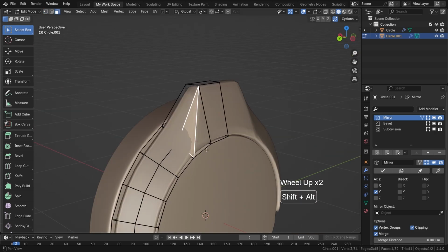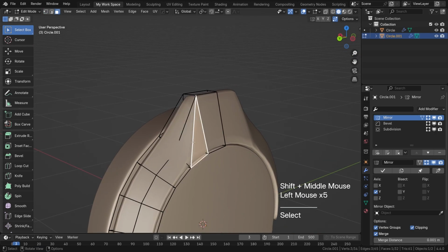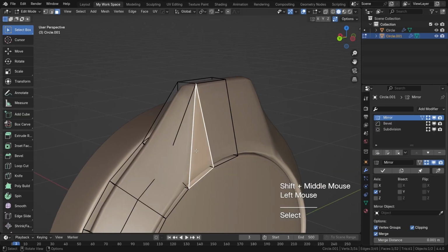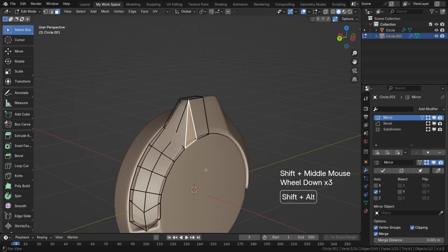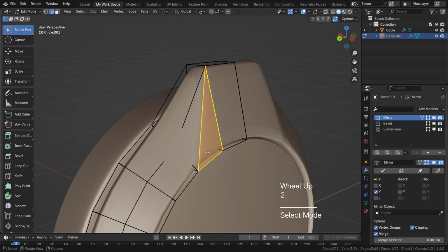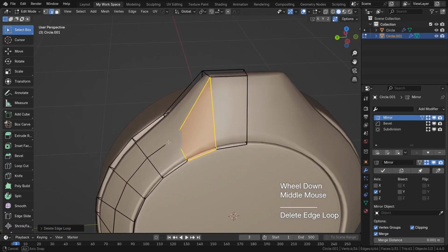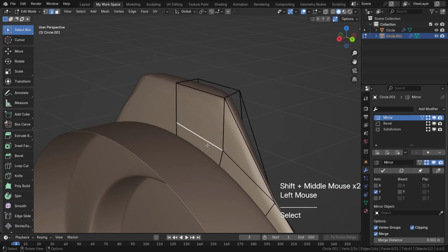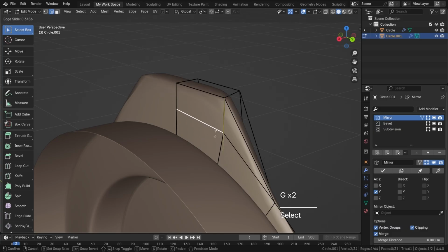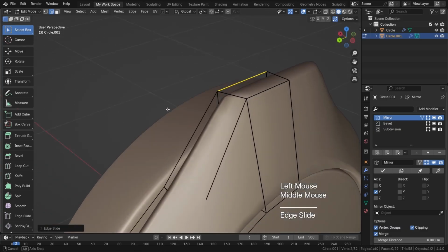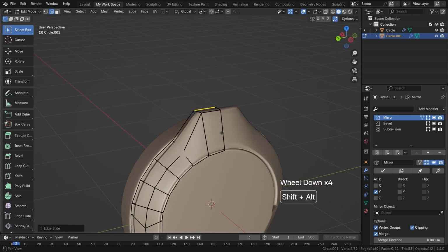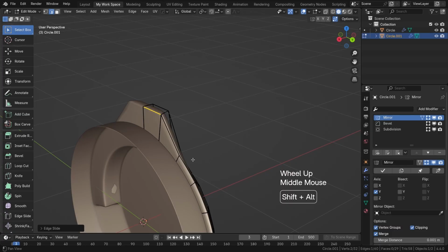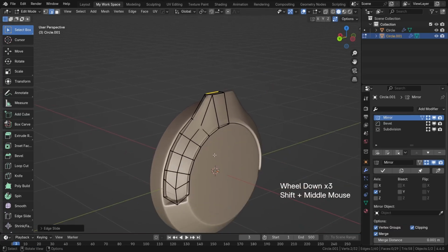Okay guys, so now you can see here we have created triangles. So we have to remove that, since we are also taking care of geometry, so we'll reroute this, and I'll select this and press X and H loop. So now this issue has been resolved. And here also guys, one triangle has been created, so I'll just select this, GG and shift it all the way upward like that. So now this issue is also resolved. Now we have all quads, so it's looking good now.